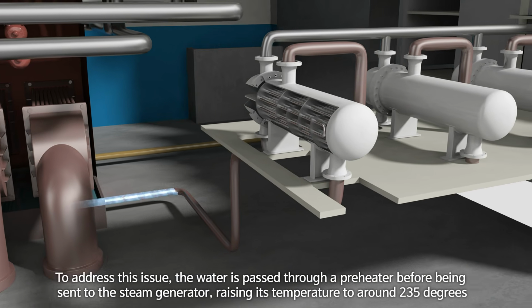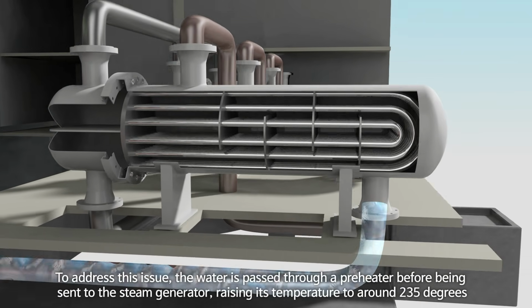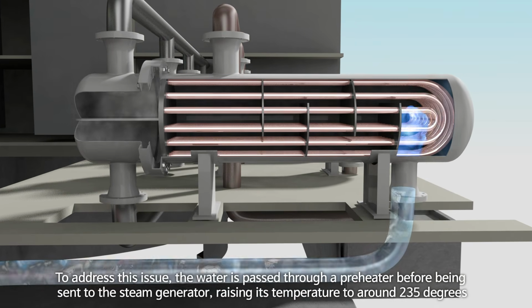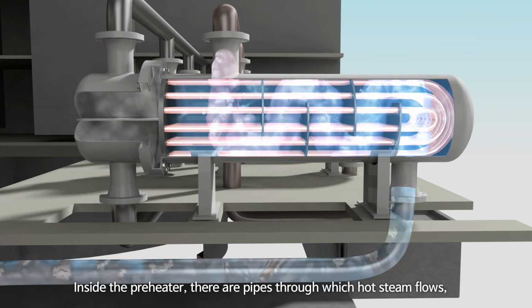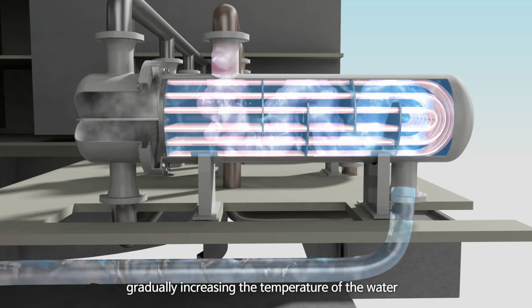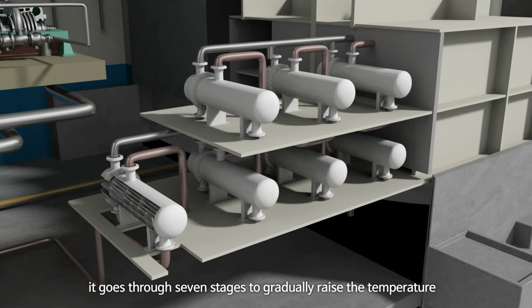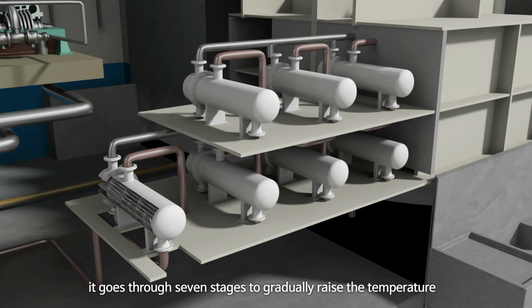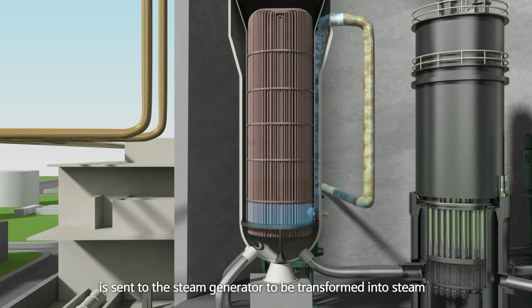To address this issue, the water is passed through a preheater before being sent to the steam generator, raising its temperature to around 235 degrees. Inside the preheater, there are pipes through which hot steam flows, and the hot water passes through these pipes, gradually increasing the temperature of the water. As the water's temperature does not rise instantly, it goes through 7 stages to gradually raise the temperature. Water, now at an increased temperature, is sent to the steam generator to be transformed into steam.